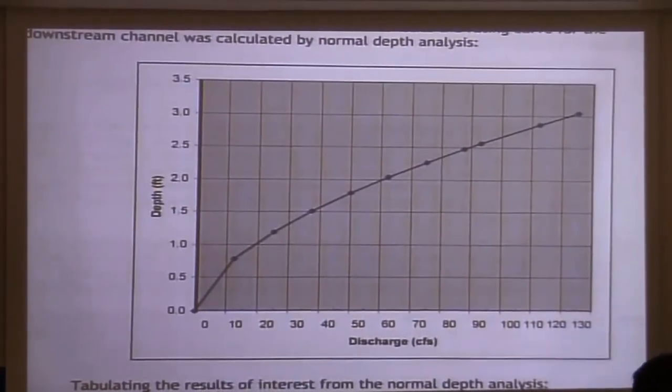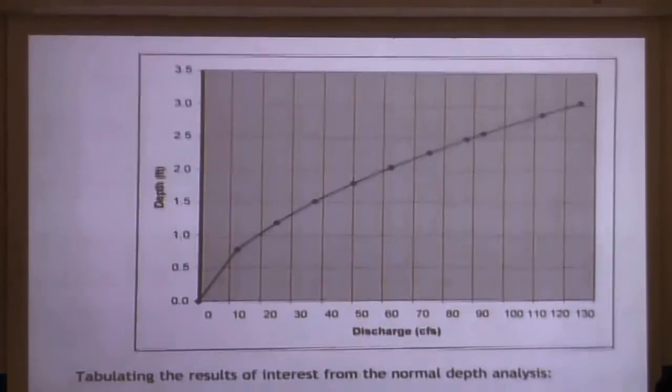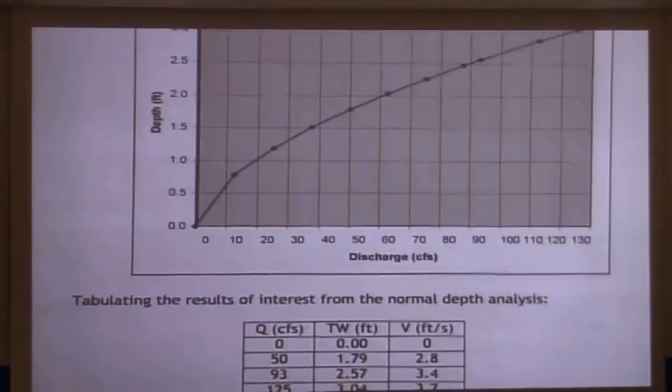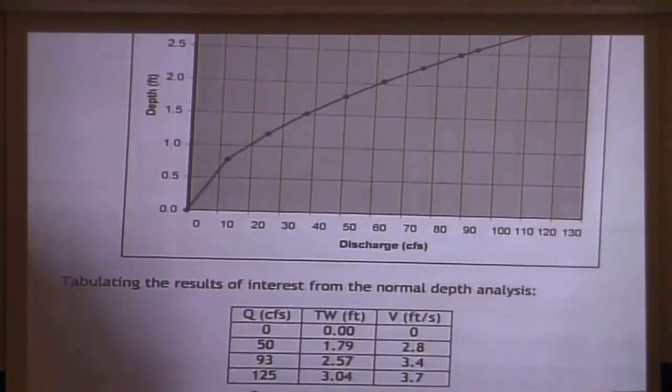Given that we have computer software nowadays, you can just generate a rating curve yourself. You just specify a minimum flow and a maximum flow. In HY-8 or the Hydraulic Toolbox, it will solve Manning's equation for all the different discharges in between, and it will generate this for you. Or it will just do the calculation directly. Okay, so rating curves, for the most part, are pretty much done automatically by software anymore. We don't need to do these by hand.